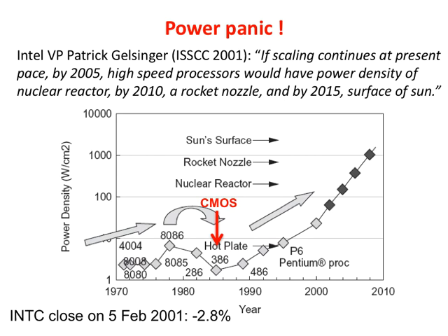Then we started to see an increase, and the first increase was due to the fact that the static power consumption became important, like here. Then at some point, they stopped the decrease of voltage. They stopped the voltage scaling. And so if you do not stop the clock frequency, you observe a steep increase in power consumption.